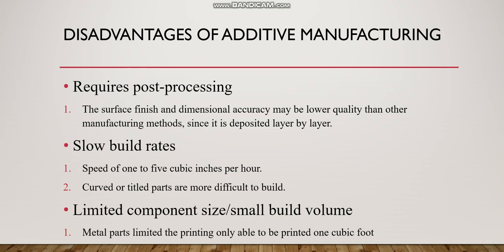Using additive manufacturing also gives disadvantages to manufacturers or engineers. First, it requires post-processing. The surface finish and dimensional accuracy may be lower quality than other manufacturing methods since it is deposited layer by layer.